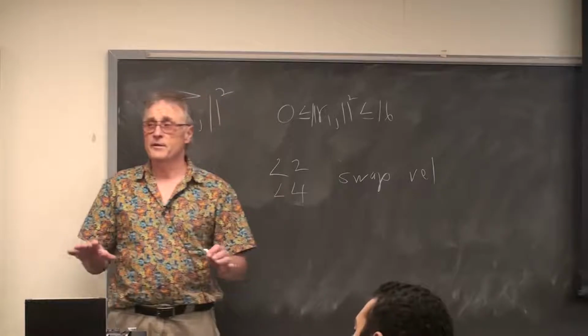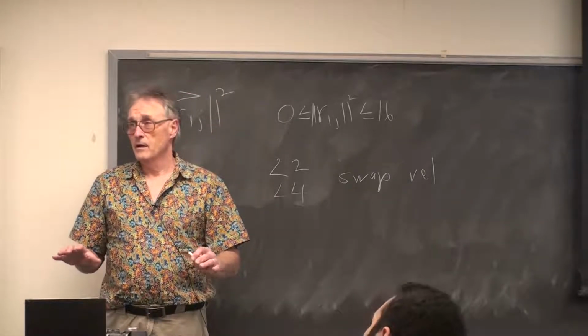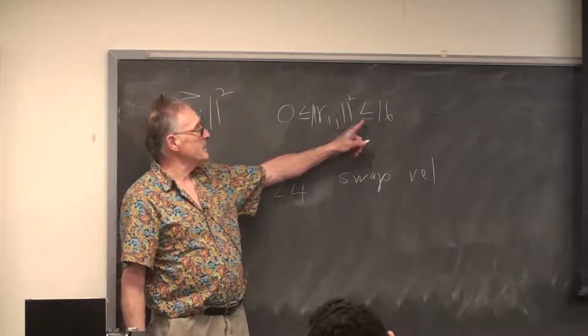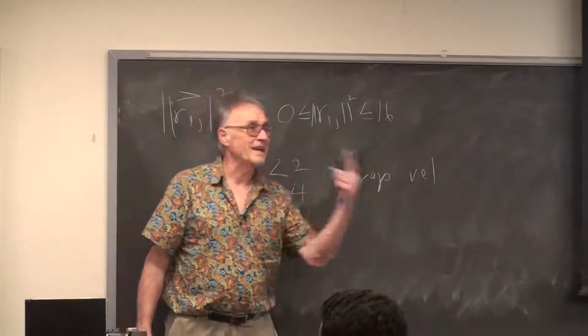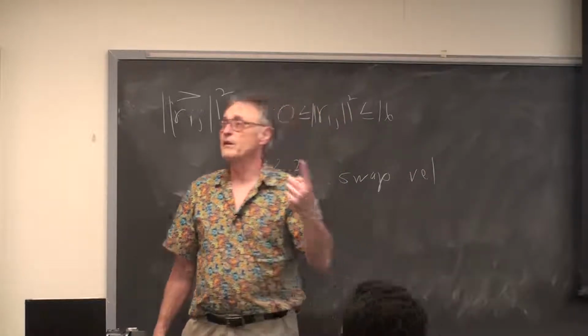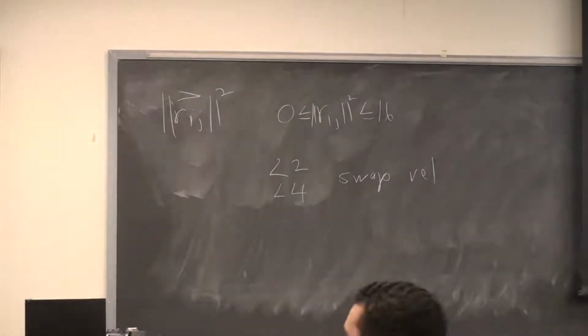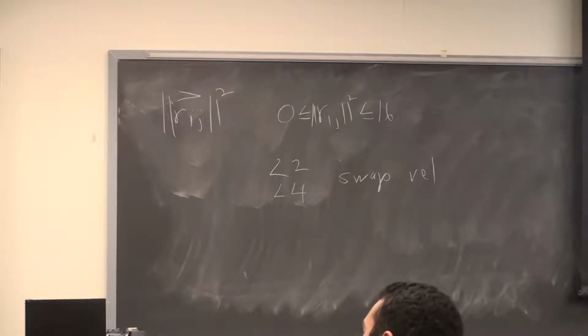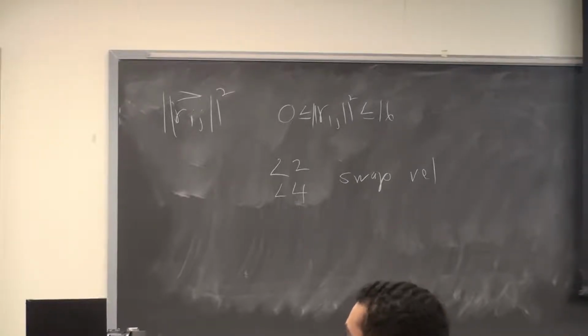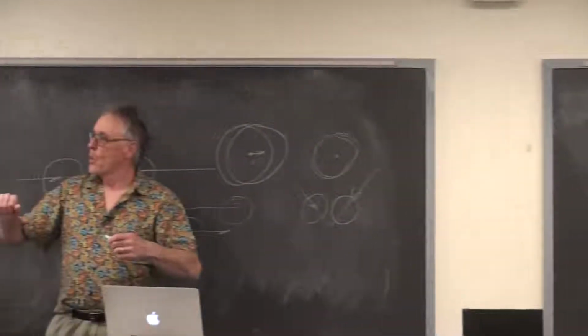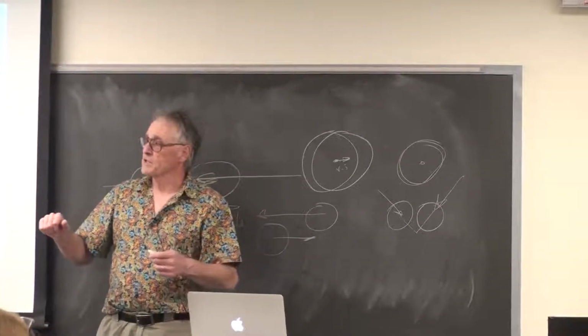But you could do better than this if you wanted. You have numbers ranging here between 0 and 16. You could treat those as indices into an array of reciprocals and use the table of reciprocals above 3 or 4, which will get you within 20%, to do the invert instead. Multiply by a reciprocal that you store in a table. It'll be a big table though. 16 entries. Well, only if you don't include the fraction. Exactly. So you don't include the fraction.